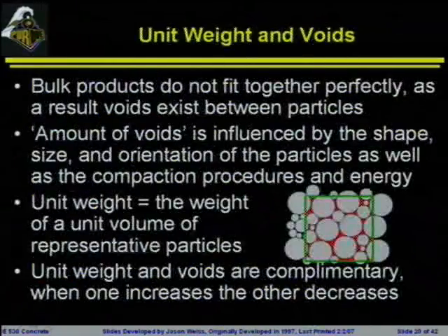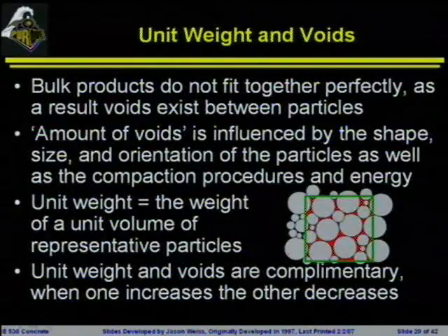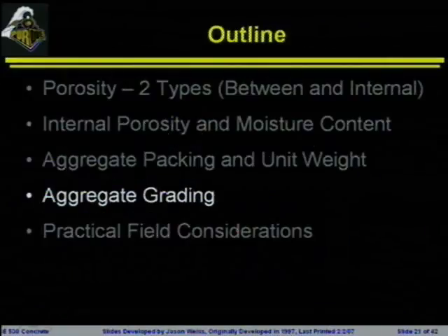One of the terms that we're going to come back to is the unit weight. Unit weight gives us a measure of this space that's between these particles. The unit weight is basically dumping a bunch of this aggregate into a bucket and weighing how much a cubic foot of this material will weigh, and that gives us an indication of particle size.